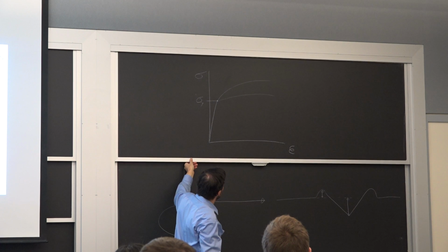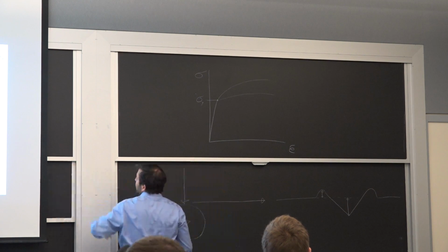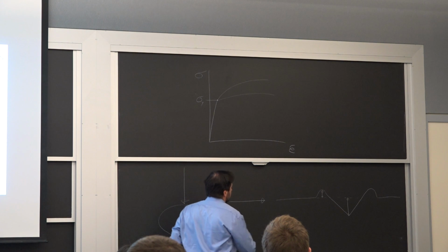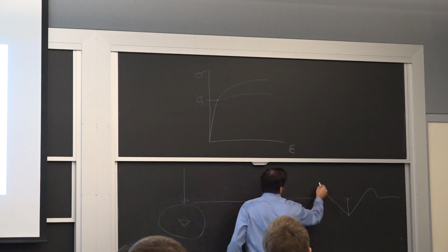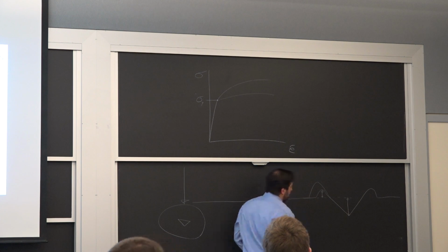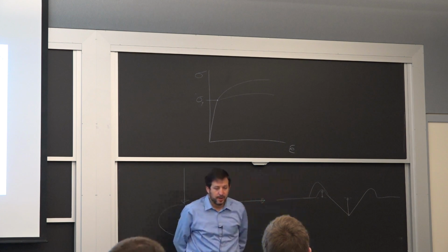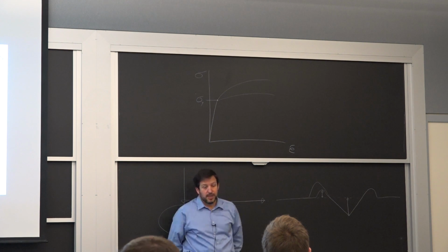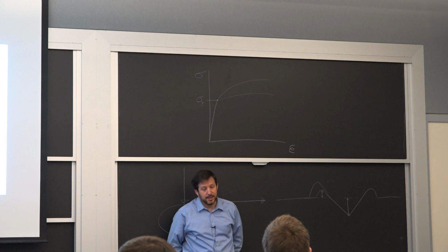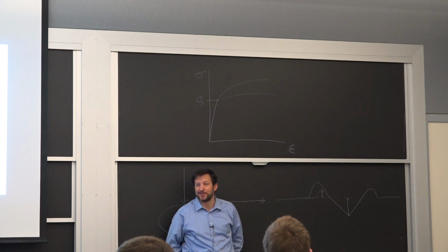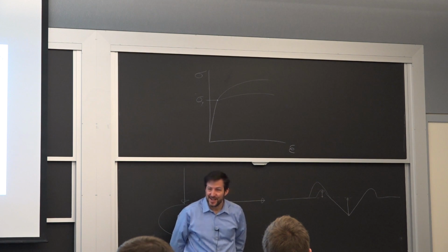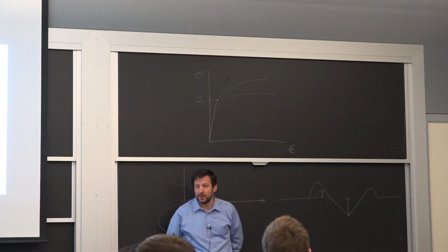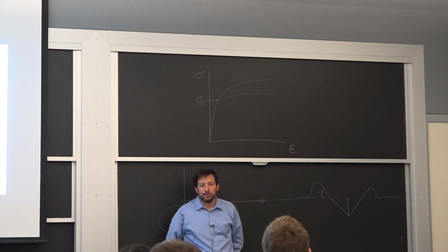So what happened during the test, you can see all these whitish, bright orange piles on each side. So this was very high, just like this. And that meant very low strain hardening. So to this point, the best explanation for that is when we were deforming the nanostructure it had grain growth. So we went from nanometer grains to much bigger grains during my test. It's not that great for wear resistance. It means that if you are going to touch the surface, you will lose some of the characteristics that you put in the first place.